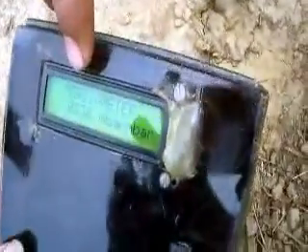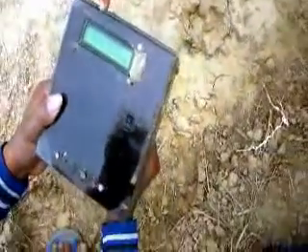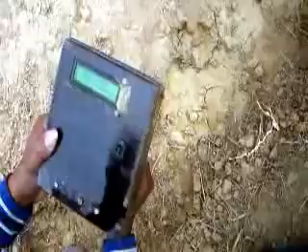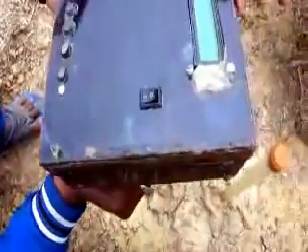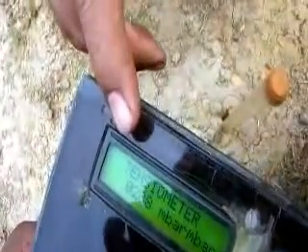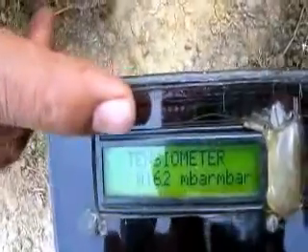So now we can see the tensiometer reading, 336 millibar. So this is 336 millibar suction head created at 30 centimeter depth. Now let us see at 45, just wait for 2 seconds. So it is finally 288 millibar at 45 centimeter depth. At 60 centimeter depth it is 162 millibar. So 336, 288 and 163 millibar at 60 centimeter.